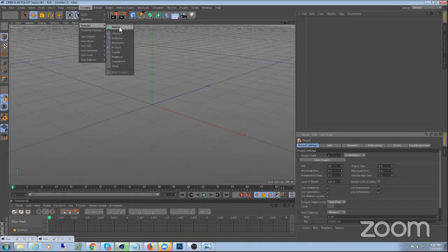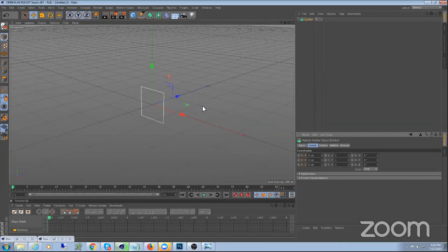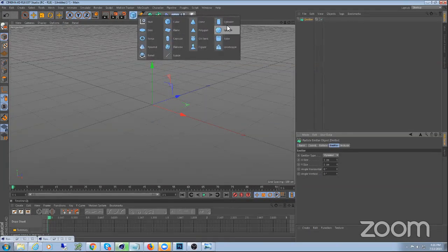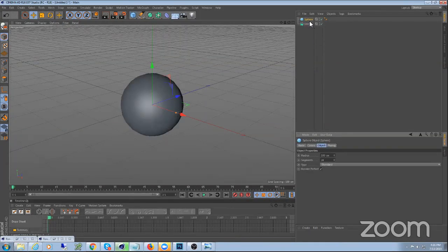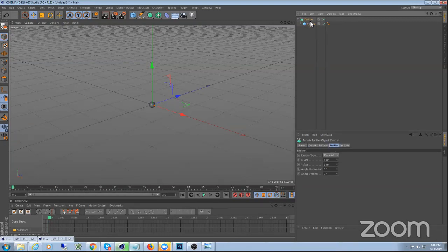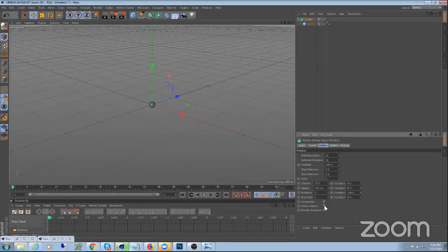Does that have something to do with the size of the particle reaching like the center part? No. Here's the emitter. Let's make it very small, 1 centimeter by 1 centimeter, and let's create spheres as particles. And let's make them 10 times the size of the emitter. Smooth particles. Put them here, and then go to the emitter, and then show objects and do tangential.